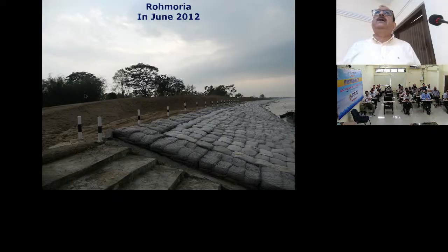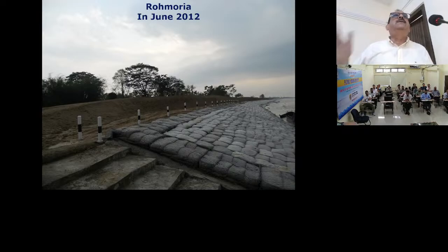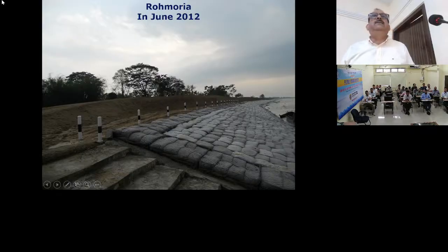So till now it is working, and after that we started using geobags extensively, especially in Assam. Now the problem is, we know the boulders. Boulders will work for say 100 years, 120 years. They are time tested. But these geobags are new to us. Even in Bangladesh, they started before us. Even there it is new. We have not tested it for the last 50 years. We don't know what will happen. The company says they have 50 years life or 100 years life. But these are not time tested.